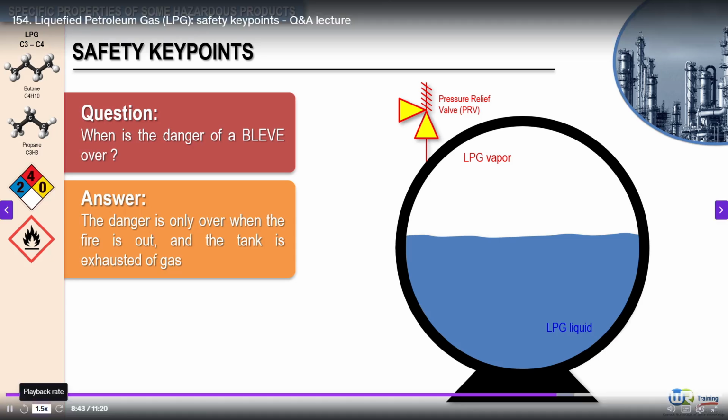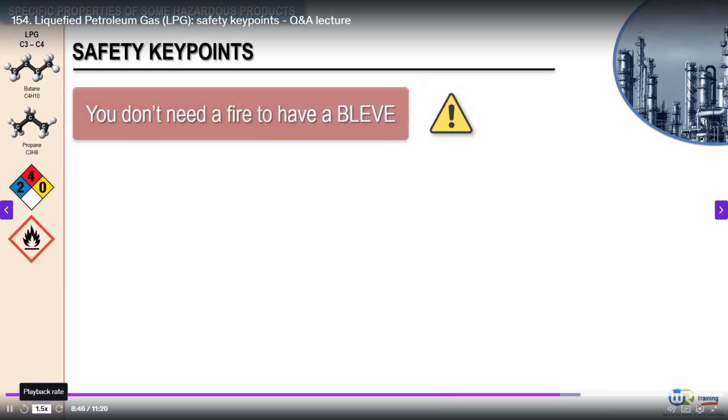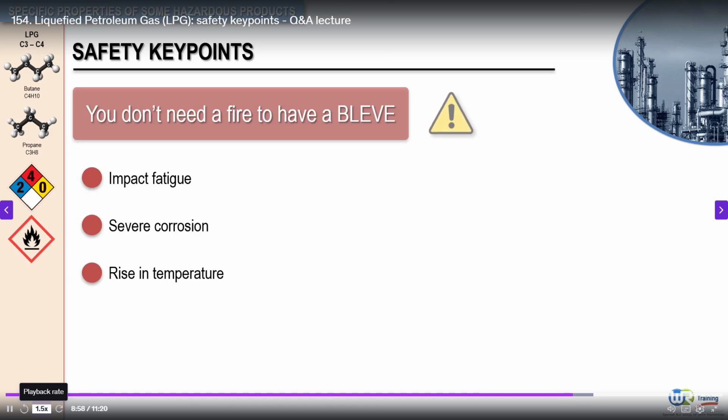Now, one final thing about BLEVEs. You don't need a fire to have one. Whatever causes a tank to be severely damaged, such as impact, fatigue, severe corrosion, or a rise in temperature, can result in a BLEVE.